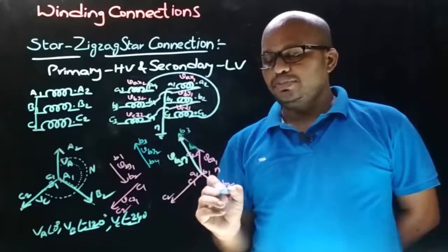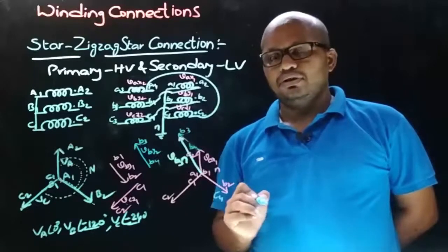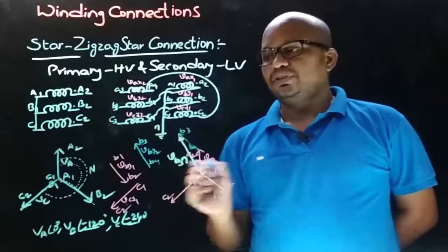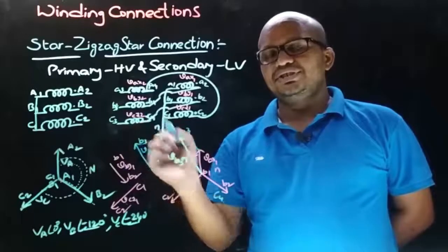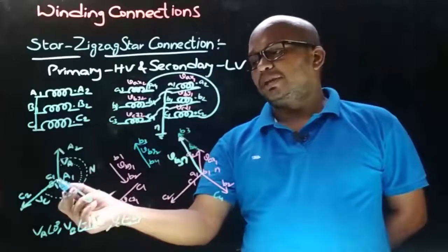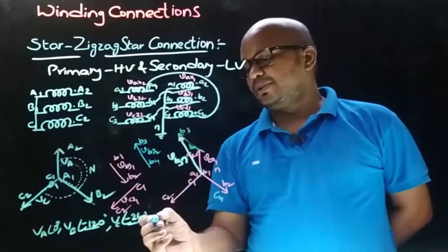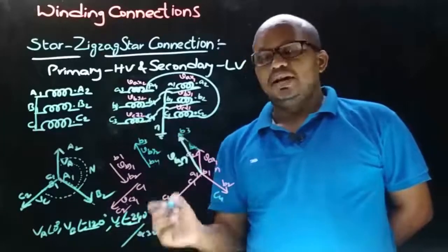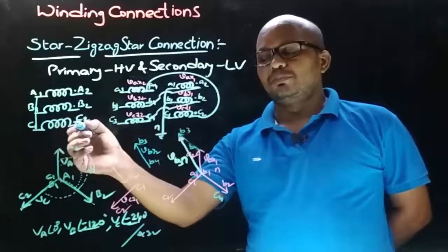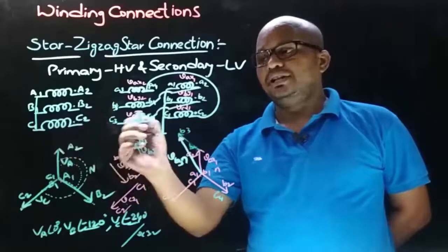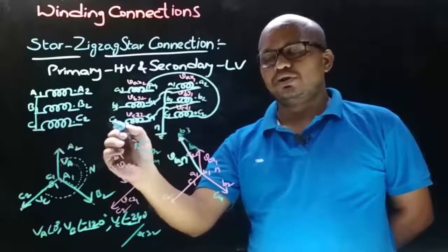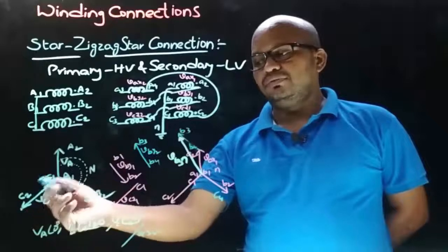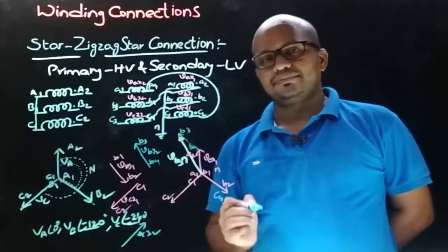And now coming to this winding connection, to dot end B2 there is C4 connection, means in phasor diagram to B2 there must be C4, means we must draw VCZ2 phasor from B2. Therefore, let's draw secondary side VCZ2 phasor parallel to primary side VC phasor somewhere here like this. And now let's decide the direction of secondary side VCZ2 phasor, and observe that in winding connection on primary side connection is taken from dot end, and here on secondary side connection is taken from non-dot end, means the direction of secondary side VCZ2 phasor is opposite to the direction of primary side VC phasor, like this.